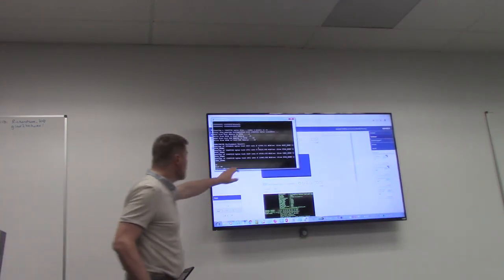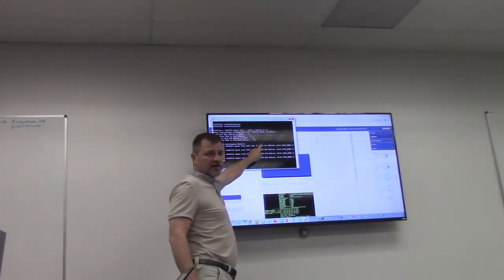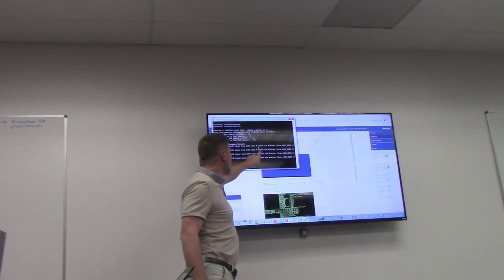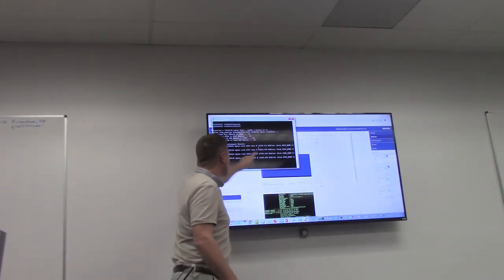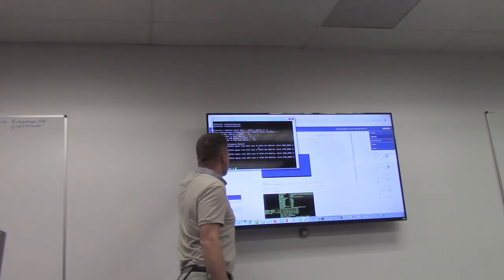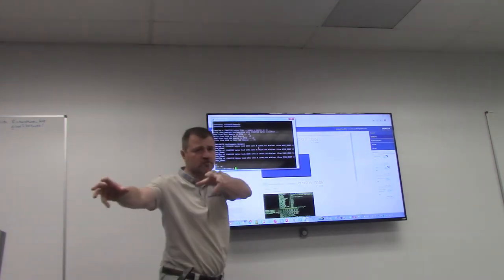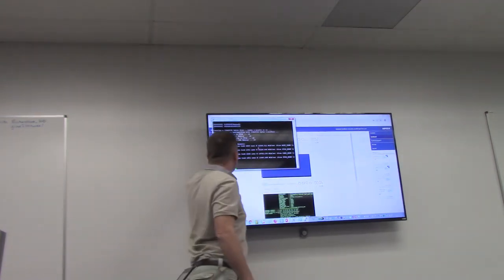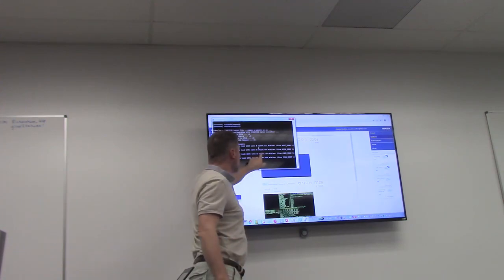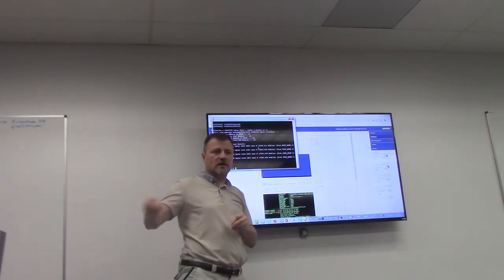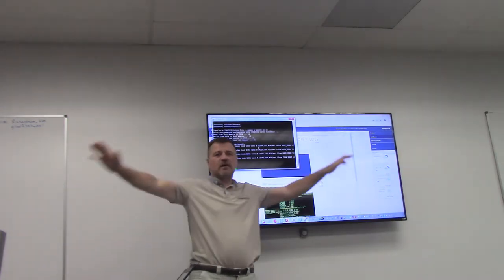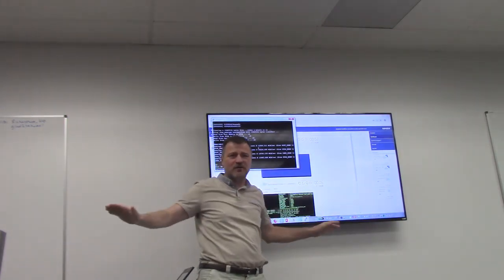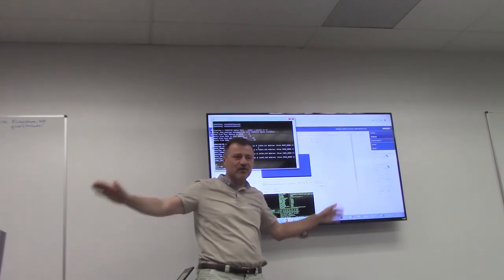Okay, and you see that the throughput on the P9, CAPI 2, 12.5, 14.2, 14.7, 13.4, are all about the same. This is copying from host memory to FPGA at 500 megahertz, back and forth, and this is the local copy to the local DDR. You see that the FPGA sees the same speed to copy. Everything is quiet around, no other bothering actions running, no other applications.